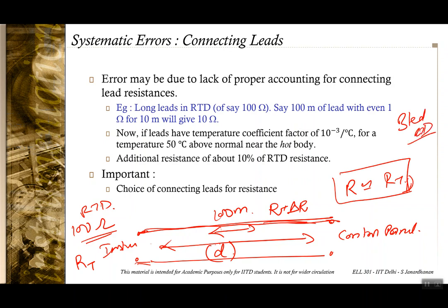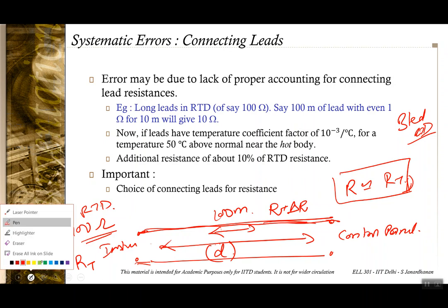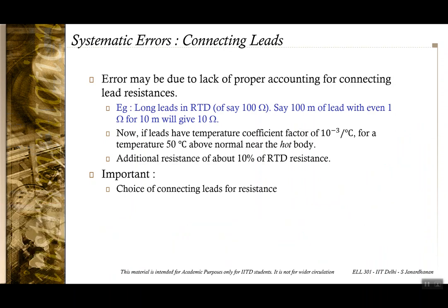In the 3-lead RTD, we took into account that the RTD leads are long, and the circuit was modified in a manner such that the resistance of the RTD leads does not really matter. Or in other cases, you can use material whose resistance is not significant when compared to the property of your measurement instrument.